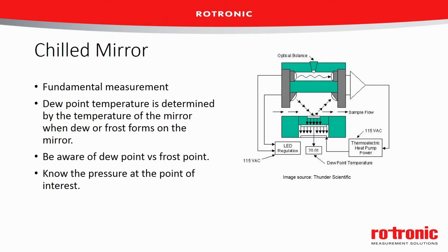And we'll move on to our last technology, which is chilled mirrors. Michael? So the chilled mirror fundamentally measures dew point. It's not measuring relative humidity. If we're getting any of those values out of it, those are being calculated.